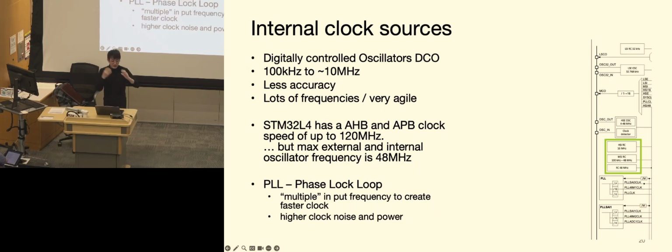Each clock cycle of the hardware timer, you try to push like 3 events in. After a few iterations, you find the sweet spot where these two signals' phases are aligned. When that happens, they use that as an internal clock source. Obviously, it's going to be a bit less accurate, but we always have some trade-offs here.